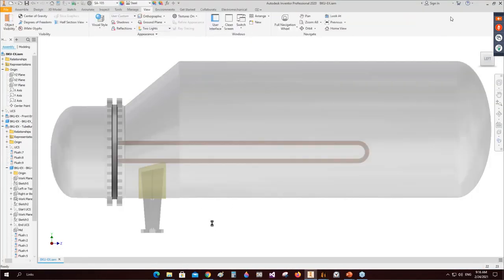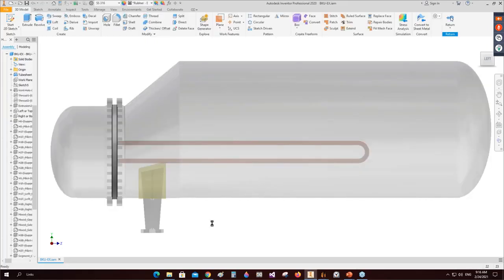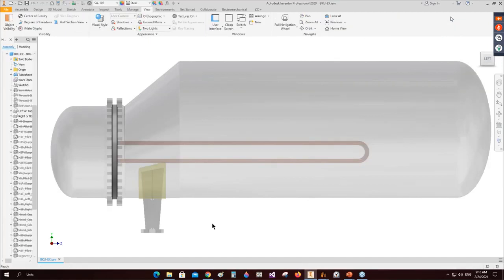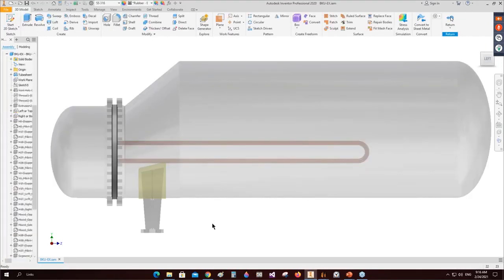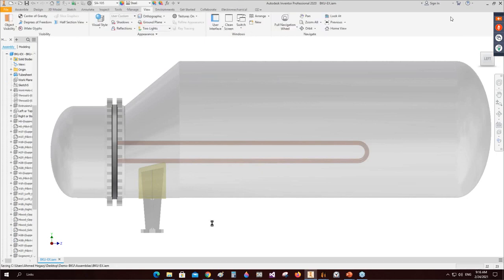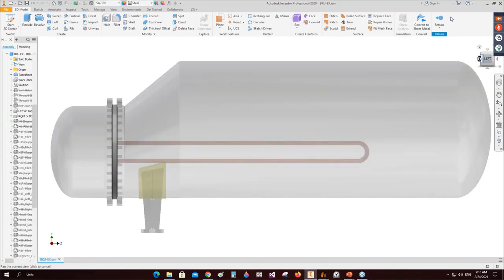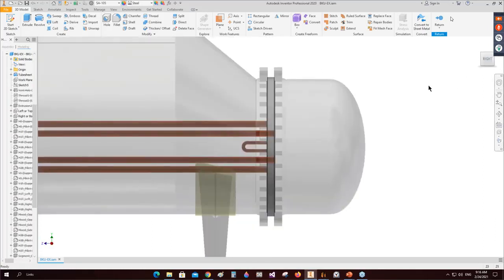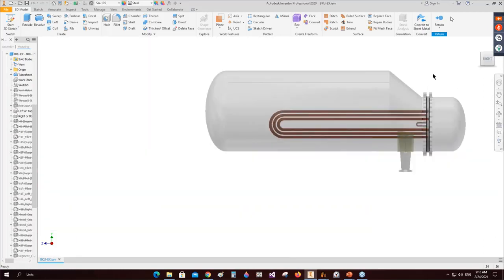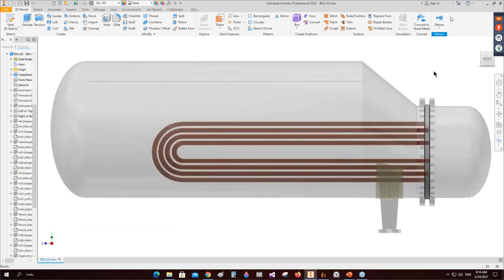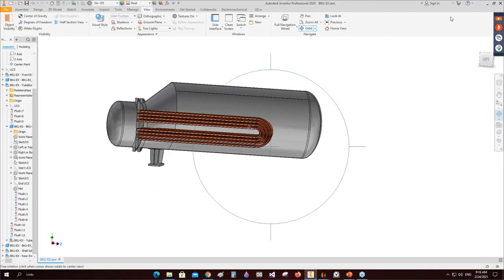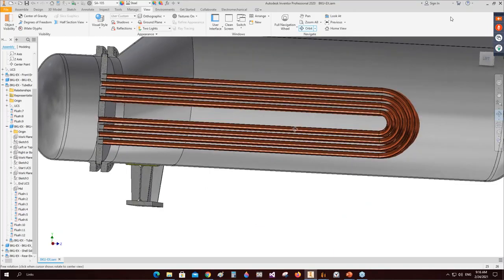And now SEG will start creating the tube sheet tooling. After that, start creating the U-tubes arrangement, and if we have tie rods, steering rod, according to our information that we create for the tube bundle arrangement, it will be reflected to the model directly. Okay, and from here you can figure that the hole is done on the model. And let's take a look at the other side. Okay, now let's click Finish, and you can figure that we have these tubes like that.